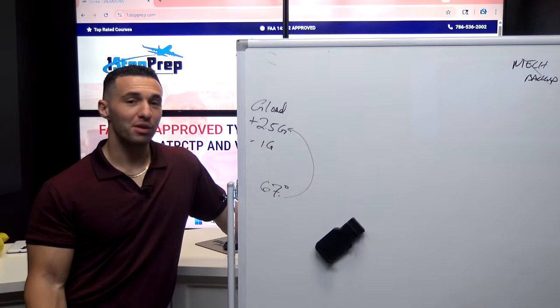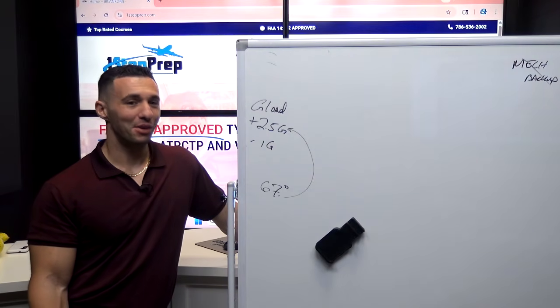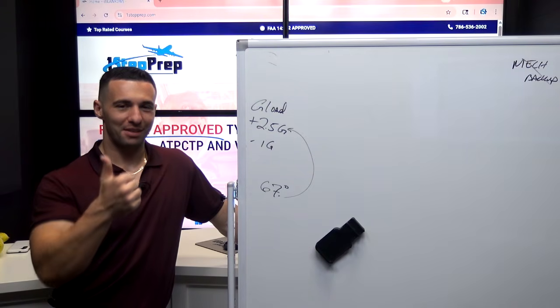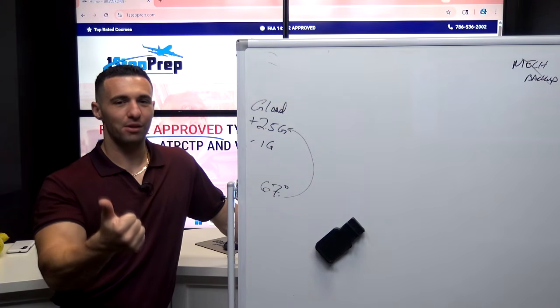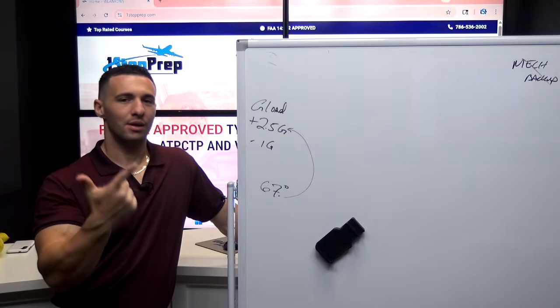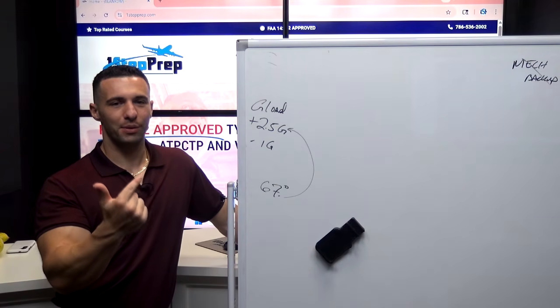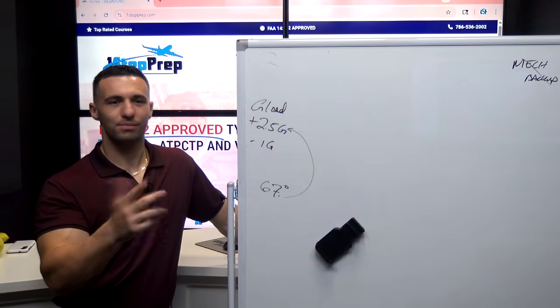Every time people say, what's it doing now? What's it doing now? The answer is always one of two things. It's in the FMA and you're just not reading it, or you don't understand the mode, or it has to do with the phase of the MCDU that you're in. One of those.